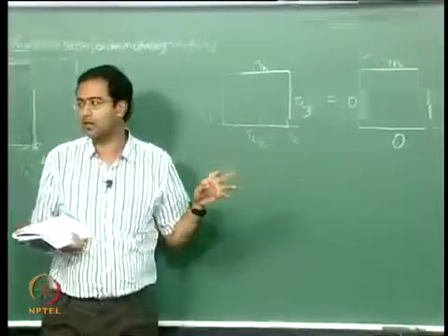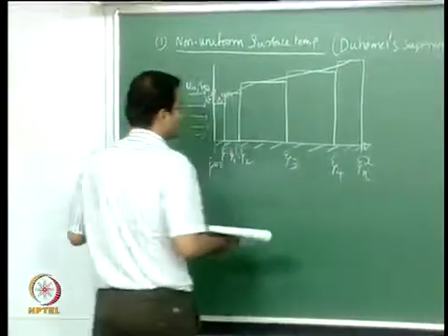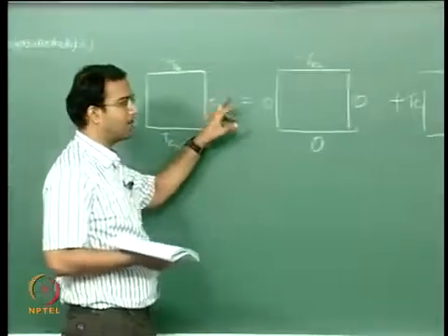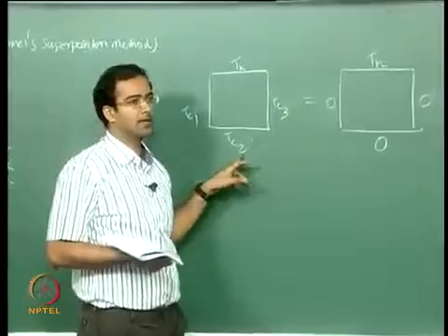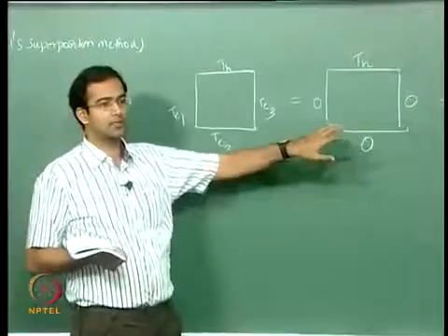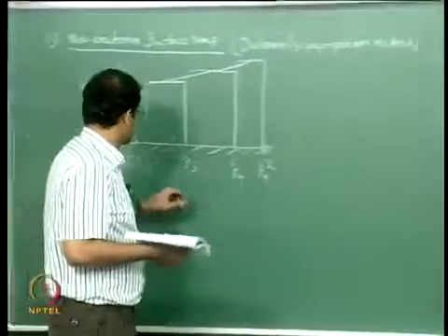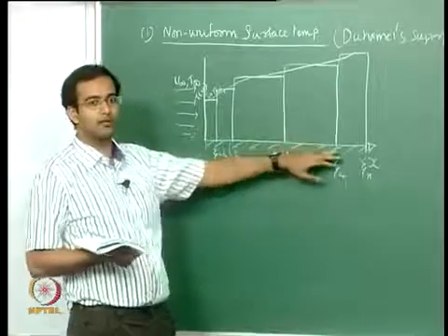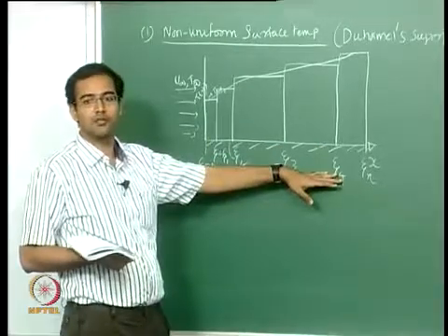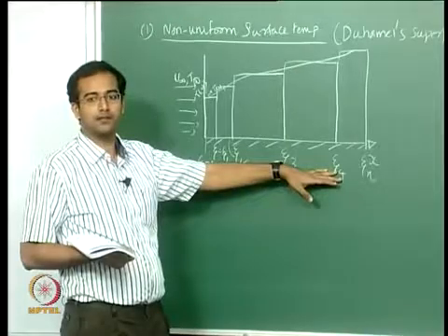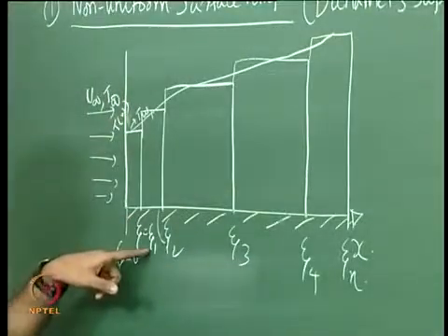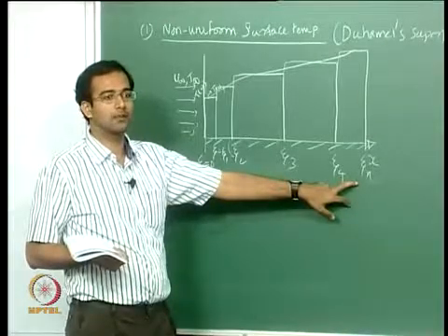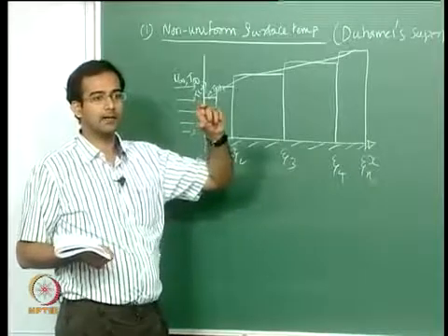The same way, if you look at convective heat transfer, the energy equation governing convective heat transfer is also linear. Therefore if you have a combination of multiple boundary conditions like this, you can superpose solutions. For example, if you have multiple wall temperatures, you can solve one problem where you have T wall 1 throughout, and the solution to that is known, plus another problem where from zeta equal to zeta 1 to the end you have T wall 2 minus T wall 1, that is the delta T wall.